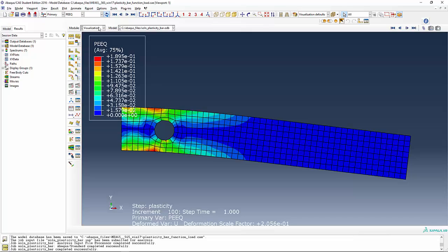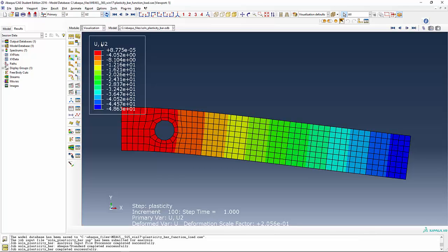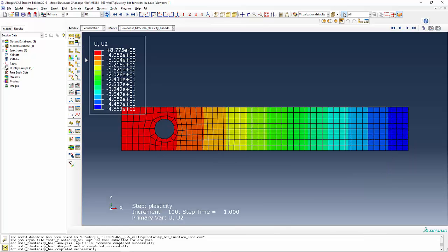Sometimes this is not really that important to you. You want to see the nonlinear behavior of this thing. In other words, you want to look at the displacement and perhaps the displacement in the vertical direction. And somebody wants you to plot the movement of the maximum displacement as a function of what? You remember load versus displacement function? After all, you want to prove to somebody that you indeed have nonlinear behavior in your system. Okay? So let's see what we can do here. I want to go ahead and plot that in the undeformed shape. Are you with me?